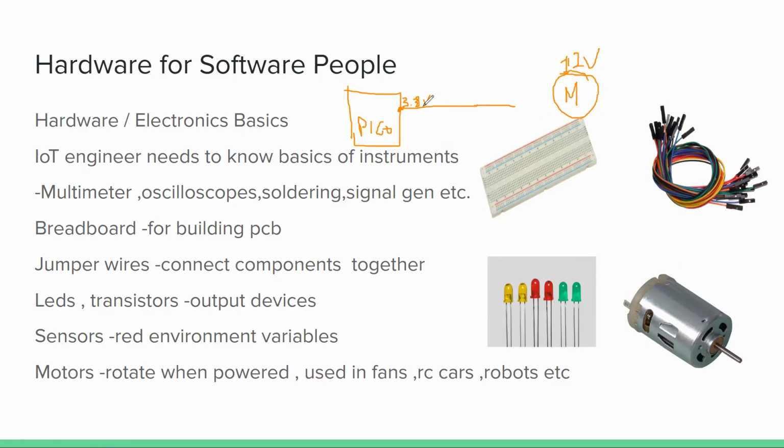Do you think the 3.3 volts from the Pico can turn this motor? That's 12 volts, and here is 3.3. No, it cannot.